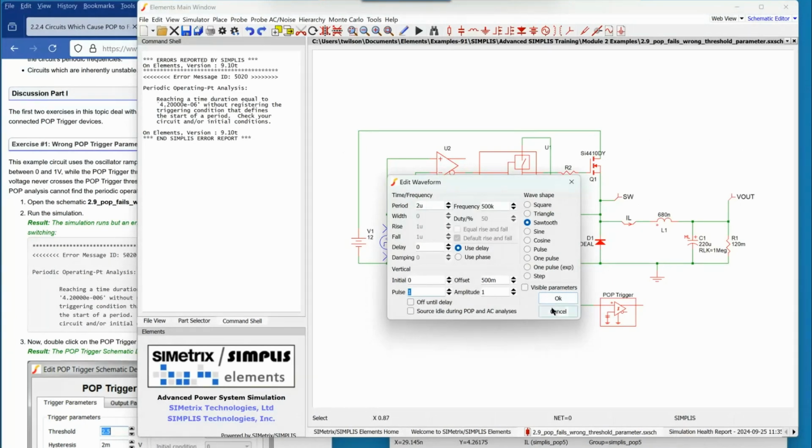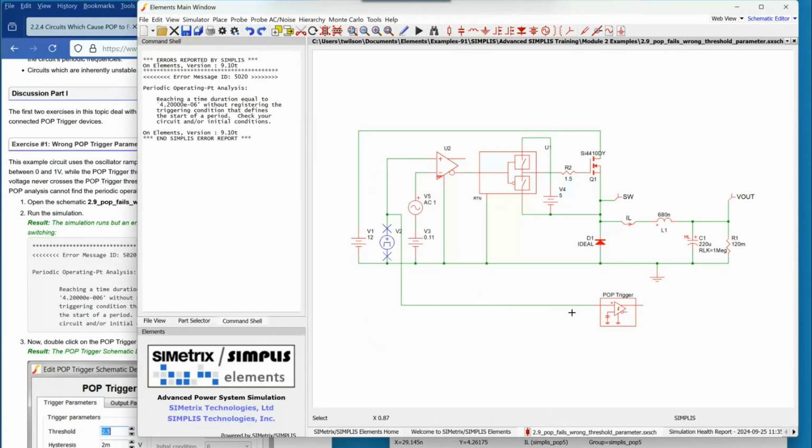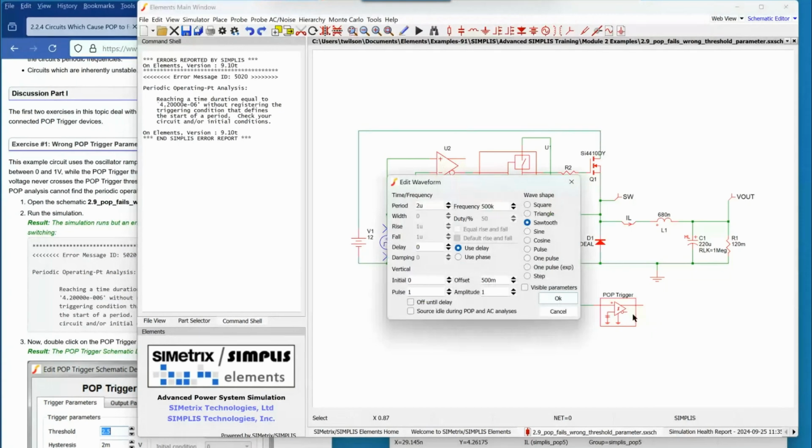So now we could change, well, you could just hook up to the comparator. Then if we had a real feedback loop, we would have the issue that sometimes the controller can get in a state where it tells the switching to stop. Here, we don't have that problem. We know the threshold over here is 2.5, so we could make this 5 volts. But now we're changing the gain of the system. That's probably not a good move, right?